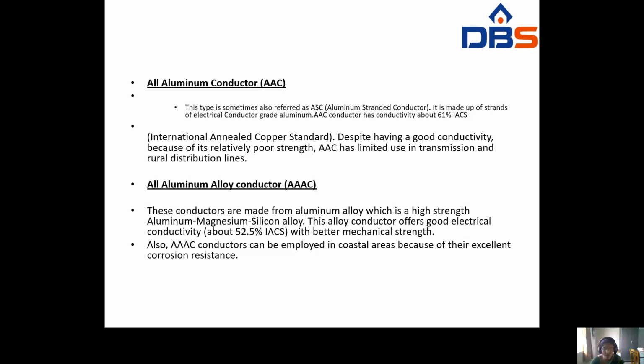Also, AAAC conductor can be used in coastal areas. Mostly this type of transmission is used in coastal areas. Why? Because they have excellent corrosion resistance. Because of this property, we are using these conductors in the coastal area.